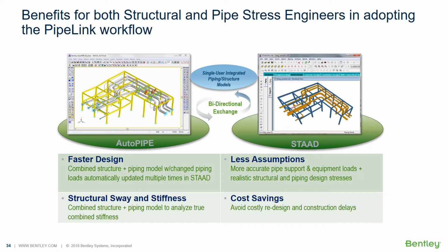This integration, it's got a ton of benefits. It really does. It's going to lead to faster design. You're combining your structure and your piping model with your changed and updated piping loads automatically. And this can be updated multiple times in STAAD. If you have to go back and forth, not having to mark up stress isometrics is huge.